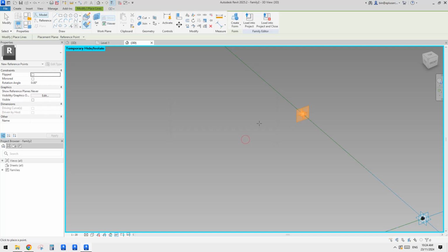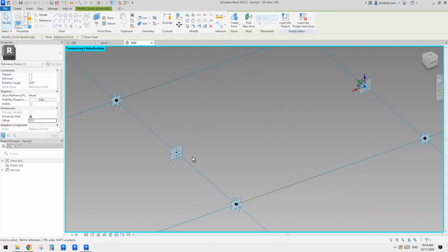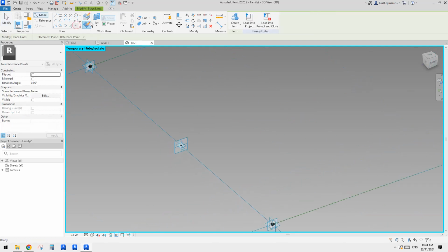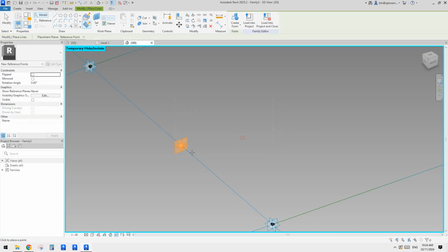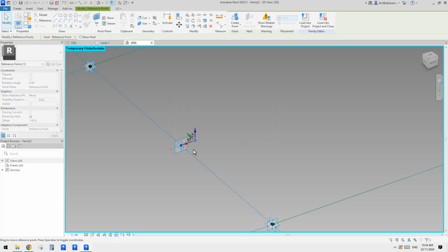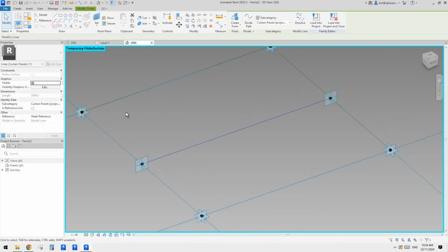Okay, so you should see this warning. Okay. And then just drag it 1 by 1, 10 by 10, and do the same thing, 1, 2, 3, and vertical, and place onto the point. Click OK when you see the warning, negative 10. Okay, so again, let's select all these points and create spline through points.